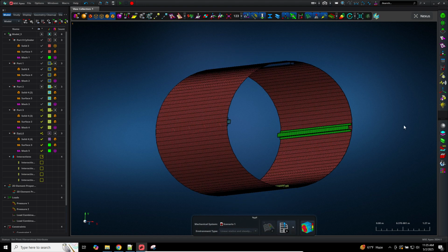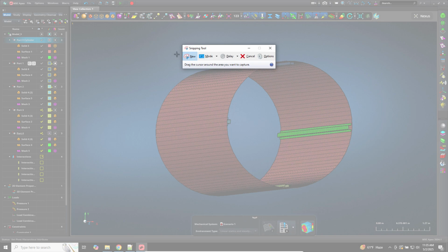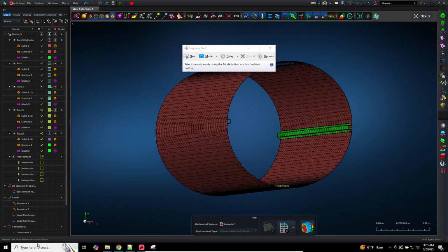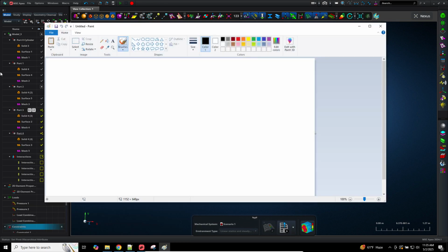Okay, now let's talk about element coordinate systems. There's a very big problem that I see new users have, and that's with the 0 degree direction for a composite laminate. So here, 0 degree direction. That is very important. You have to know which direction is your 0 degree direction, or you're going to be doing your work completely wrong.